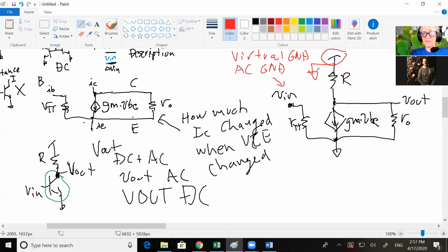Okay. 3 minutes, I think we can do it. A good step to do after you've zeroed all your DC sources and you have your circuit drawn out is to see if there's anything you can simplify or prettify. Do you see anything you can maybe get rid of, one branch somehow?